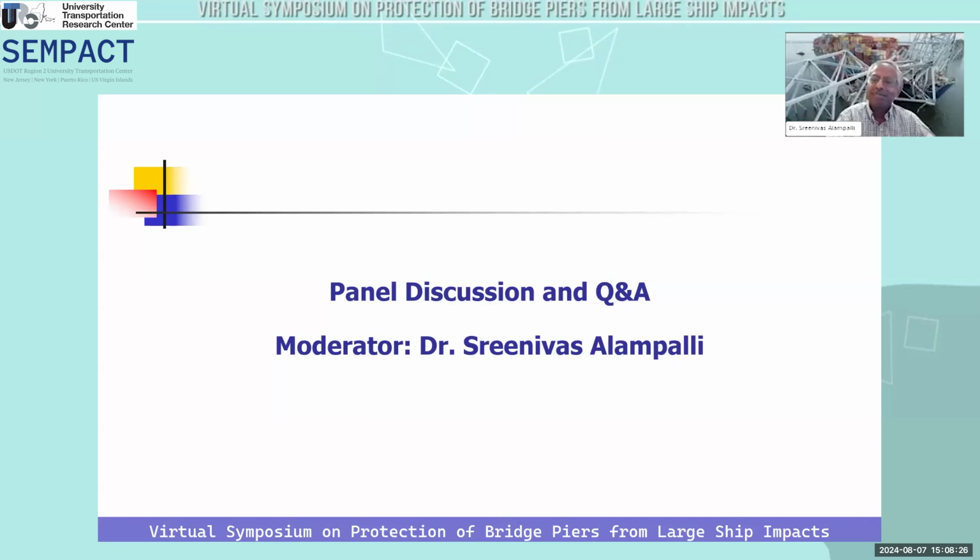Yeah, thank you. Well, I think probably the key one is rising sea levels and how that changes things, because that can have quite big impacts on the probability and also, if you like, the point of collision and impact on a bridge pier. So certainly when you're looking at things over a design life, I would say sea level rise would be a key factor in the assessment and calculation of risk.